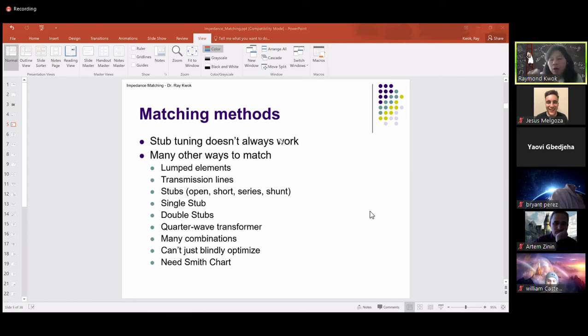And you cannot even model it because it's hard. Let's say you are putting it next to the wall. How are you going to model the capacitor? It's very difficult. So that's why tuning on the bench becomes very important, and that's what the technicians typically do. Okay. But if you have to design something, for example, we said earlier, if you want to design an amplifier, you buy a semiconductor chip and you have to design a matching circuit. You won't rely on the technicians poking, right? That's not how you do it. You actually design the matching network into your circuit.